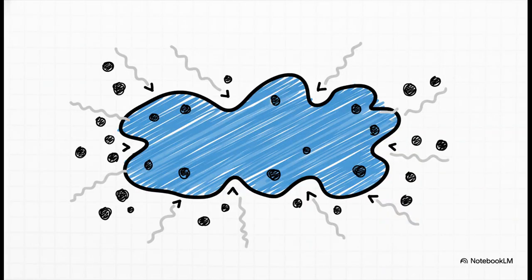And you guessed it, just like thermophoresis, we figured out how to use this effect in a big way. In things like Venturi scrubbers, they mix hot, dirty gas with a cool water spray. Water vapor starts condensing onto those little droplets, and that creates a Stefan flow, a conveyor belt, really, that pulls all the tiny pollution particles out of the air and onto the droplets where they can be collected.